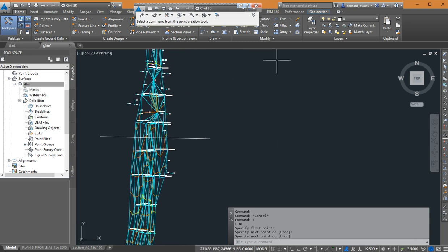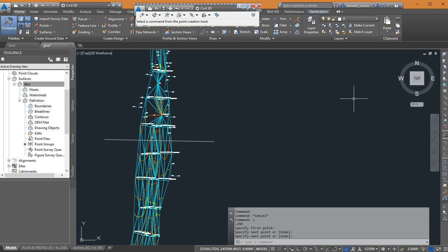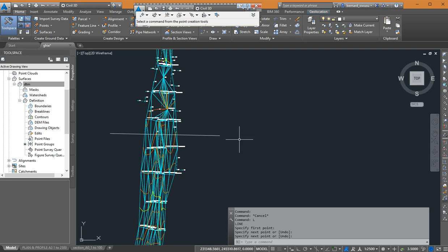So please, what we are going to do is that we are going to divide our screen into two, so that I have two viewports for the model space. Please, are you getting what I'm saying? So that we can see the plan and also the cross section that we are going to do. What we are going to do is just a quick profile. It's a temporary profile. The moment you save the file, it goes, or if I delete the line, it also will go. We just want to appreciate what I mean by the break lines, how the break line will have an influence or effect on the surface.